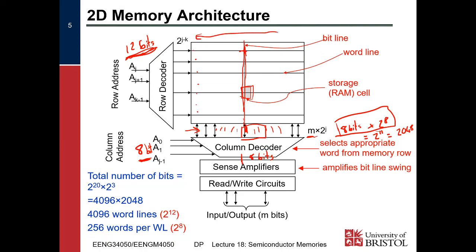So this is 2 to the 8, this width multiplied by height, which is 2 to the 12. So you have 2 to the 20 entries in your memory, but the row decoder only activates 2 to the 8 of them, which is one row, and then your column decoder selects one item out of that 2 to the 8. Does that make sense? Yes. Thank you. Yep. Brilliant.